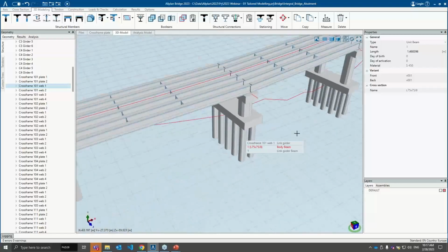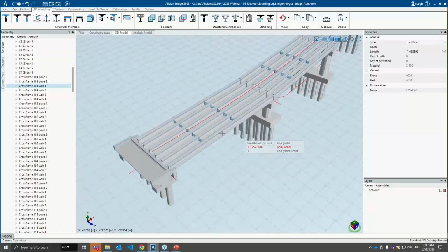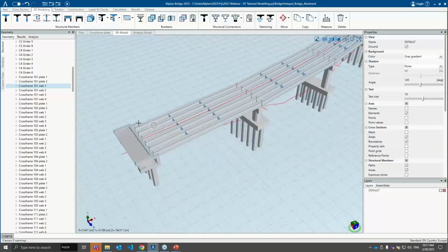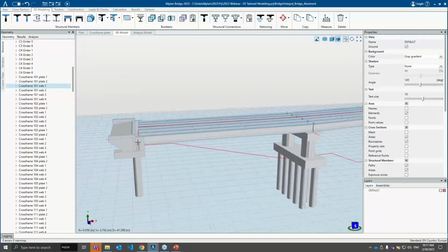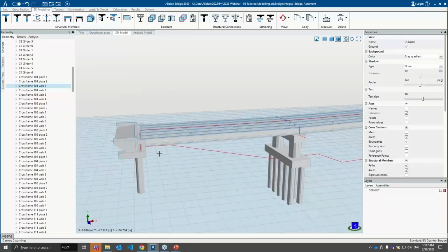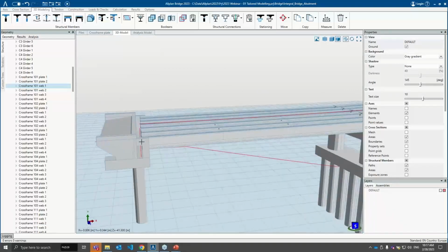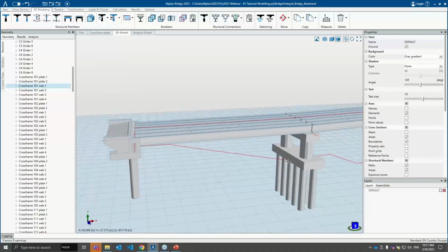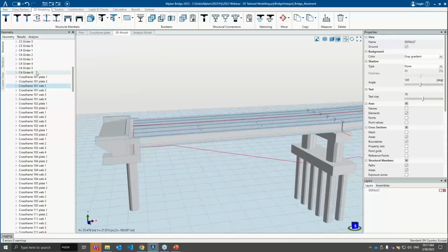So basically we can also manipulate the placement or the shape. Once we have the girders and the link girders defined, we focus on the creation of the abutments. Usually when you create a link girder, or when you create a girder bridge, you start with the abutments or the substructures, because these substructures are the guide for the length and the position of the girders.